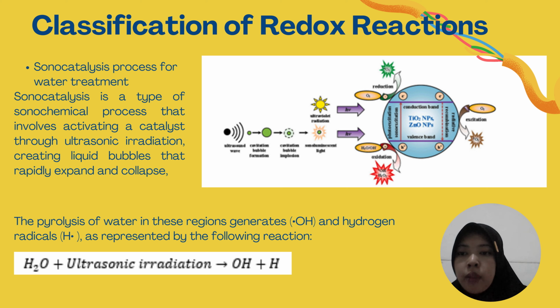The third classification is the sonocatalysis process for water treatment. Sonocatalysis is a type of sonochemical process that involves activating a catalyst through ultrasonic radiation, creating liquid bubbles that rapidly expand and collapse, such as the image in this slide. This process produces several phenomena, including generating hot spots and sonoluminescence.